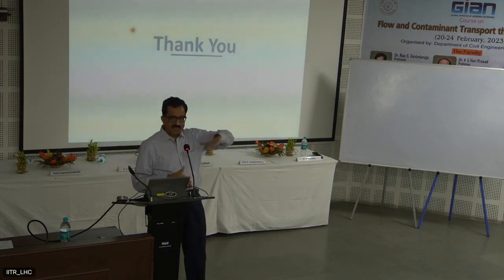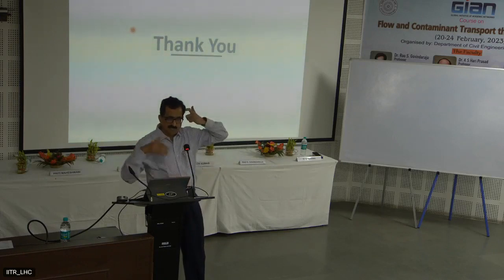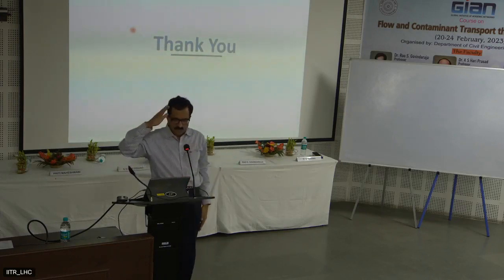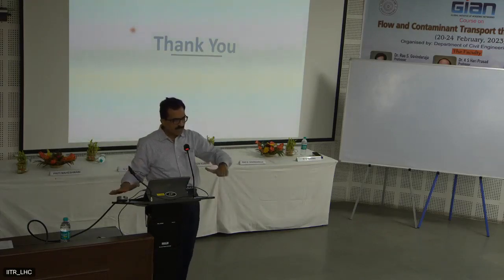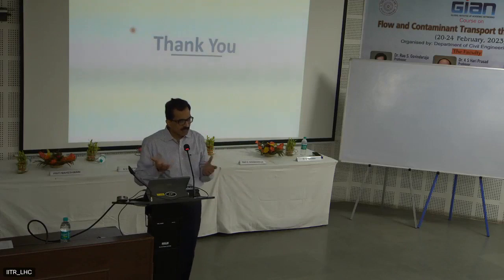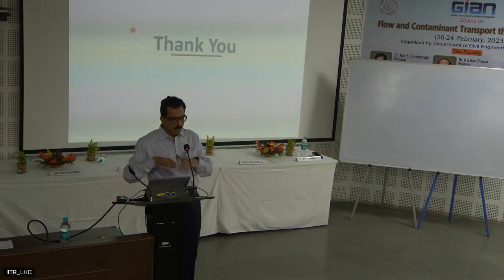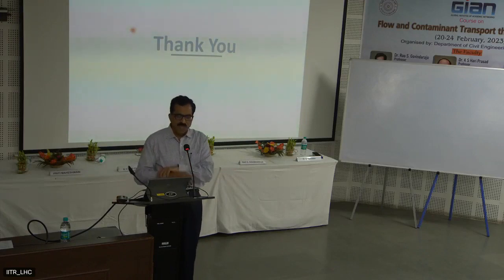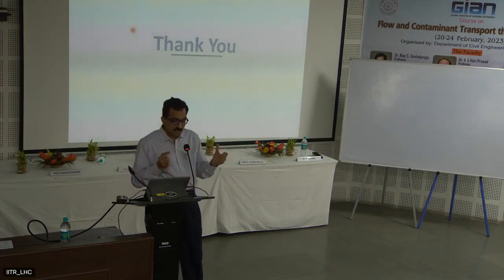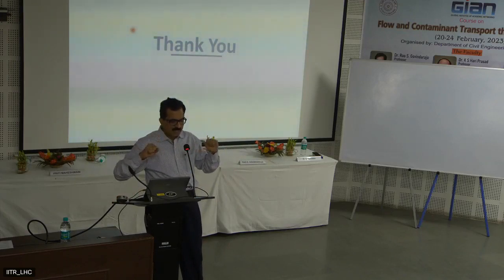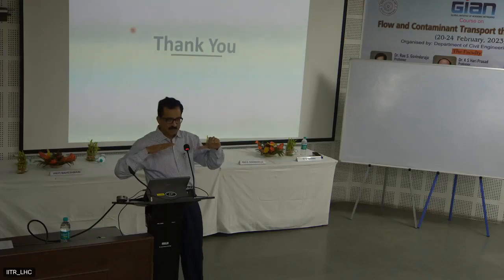Anything that is sitting on top, let's not worry about the atmospheric pressure, but anything that is overburden pressure, whether you build a huge building or whatever, is going to exert a load which is being borne by both soil and water. If you remove some of the water, then the load that is being borne by the water is transferred to the soil. And the soil then will have to bear the load. Soil particles by themselves are not going to be very compressible.